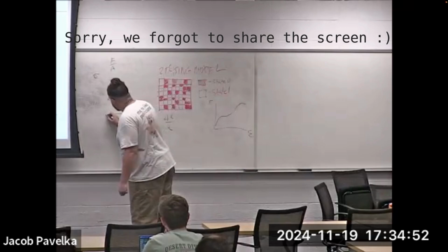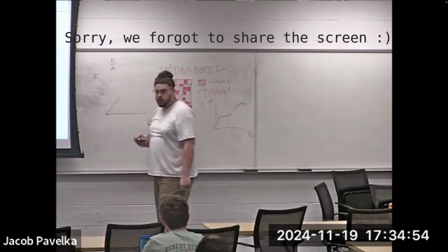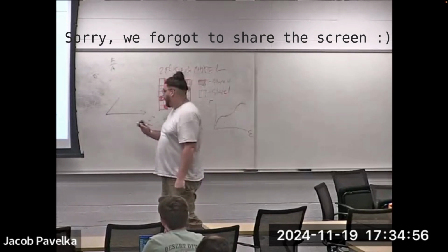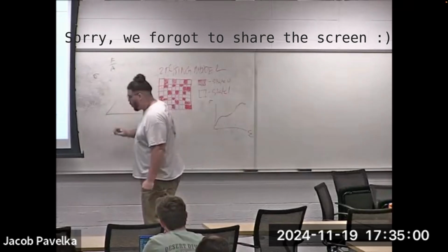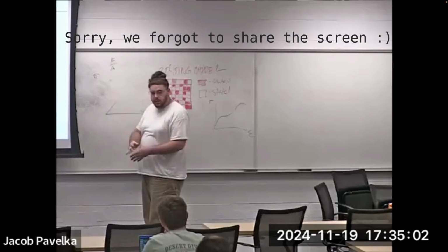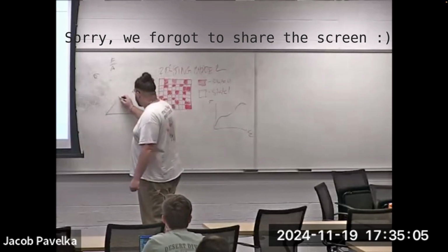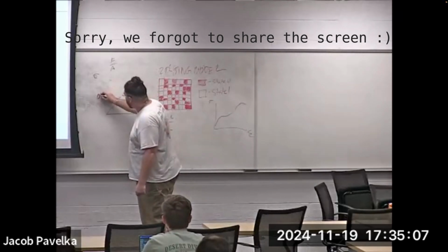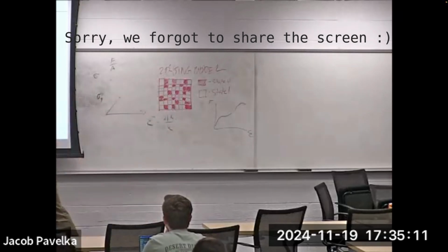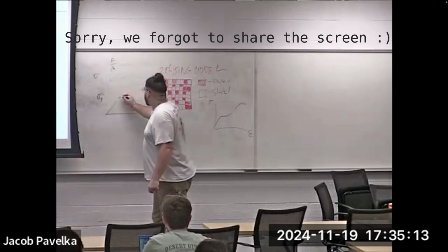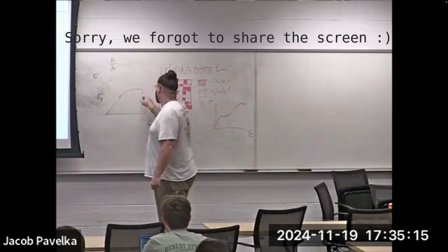So when we talk about elastic behavior, there's typically a linear relationship. And if I brought it to this strain level and then I released it, it will go back. It'll dissipate all its internal energy and come back to this state. Then we go to plastic. So there's this sigma y, the yield stress that's defined here. Then it's going to start to do something nonlinear.